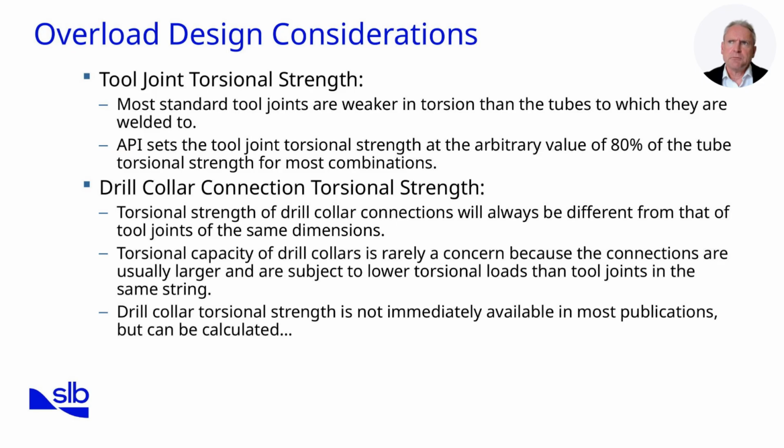Third, makeup torque must be tightly controlled. Correct torque ensures the connection is properly preloaded, distributing stresses evenly across the threads. If makeup torque is too low, the connection risks loosening and backing off downhole, a catastrophic failure mode. If too high, the threads may be overstressed or cracked, leading to reduced life. The overarching message here is that overload design is not just about body strength, it's about how the weakest elements in the system, usually connections, interact with real torque and tension loads. Managing these considerations is critical for a reliable string.